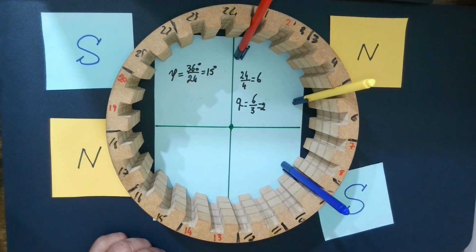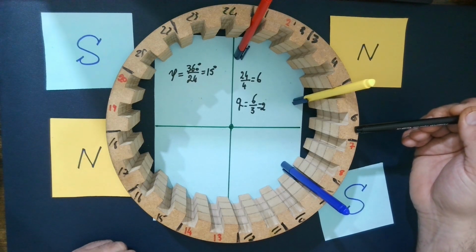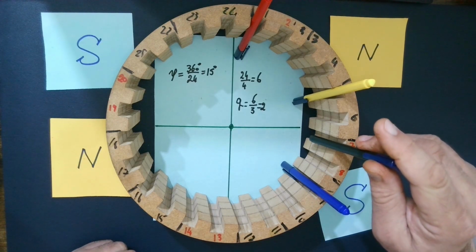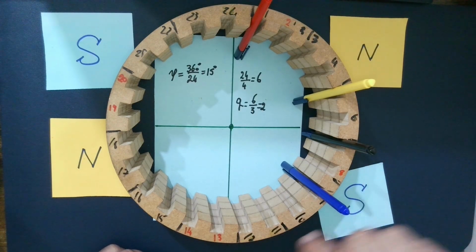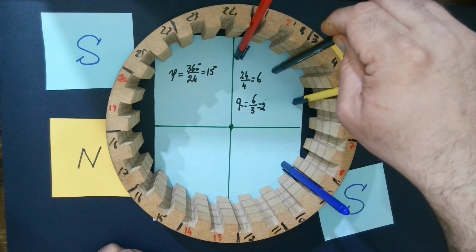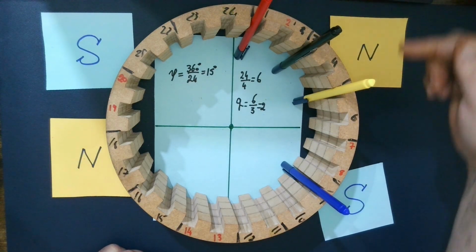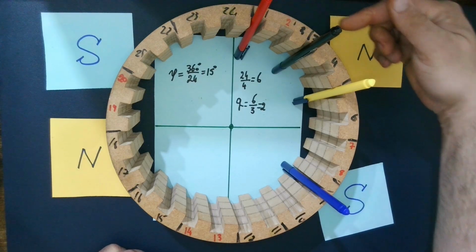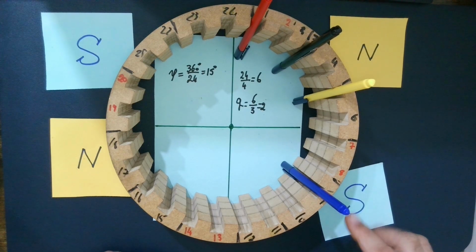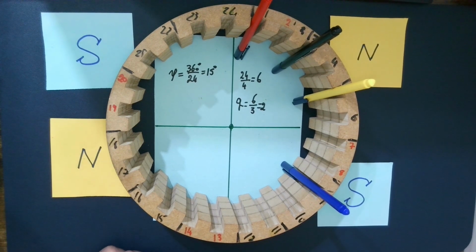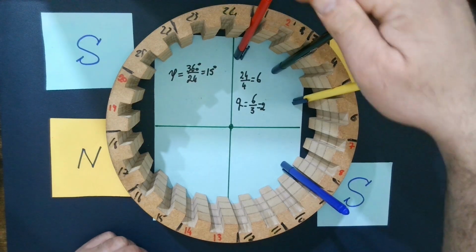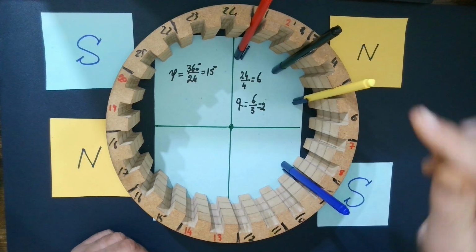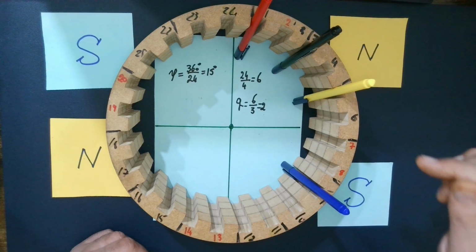So where is the return of phase A after 180 degree electrical? So here we have 90 degree mechanical. If we multiply that one by 2, so at slot number 7, we are going to start A dash. When we continue in this pattern, C dash will be at slot number 3. Under each pole, we have here all phases, A, C dash, B. And we are going to have that one the same for this pole and this pole, this pole and this pole. Right? So now we satisfy all the conditions. Each pole accommodates all phases. The phase displacement will be 120 degree electrical, and the start and finish of each phase is 180 degree electrical.